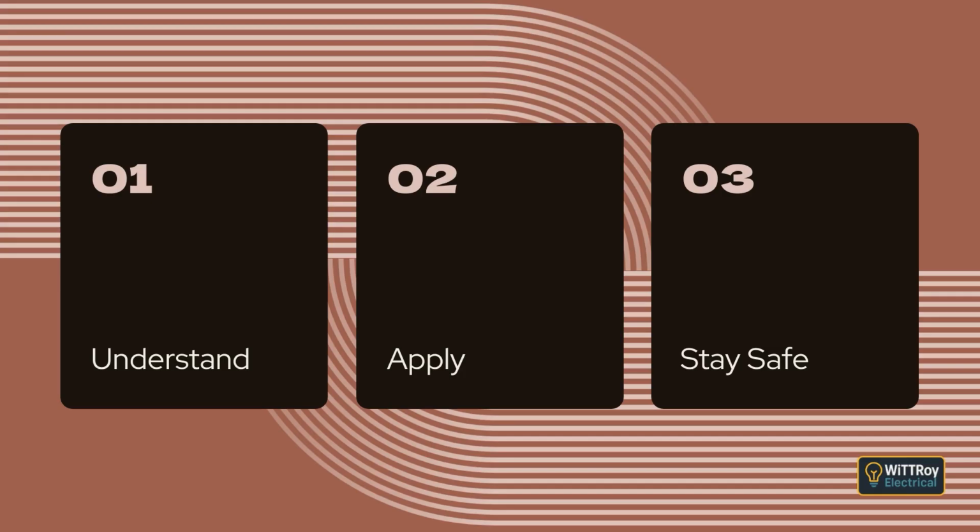Clause 2.6.2.3 Protection against initiation of fire. Clause 2.6.2.3 explains that RCDs can also help reduce the chance of electrical fires caused by insulation failure. This is not a compulsory part of the standard, but a Type S RCD with a higher rated residual current, typically 100 to 300 mA, may be used where extra fire protection is wanted. This is in addition to the requirements of Clause 2.6.3. These devices do not provide personal shock protection. Their purpose is to limit overheating of insulation and reduce fire risk.